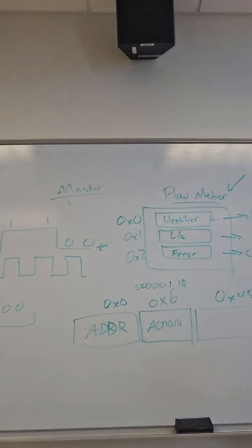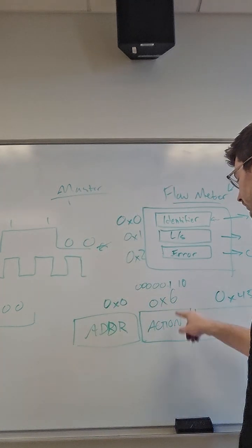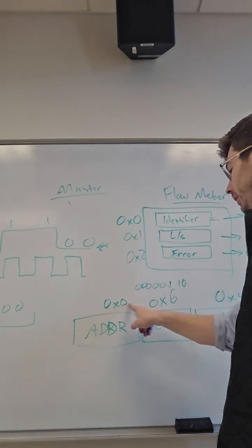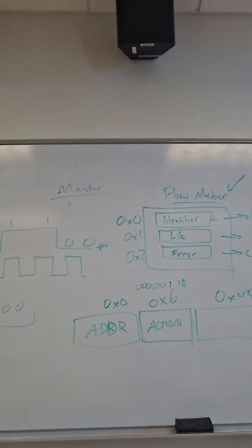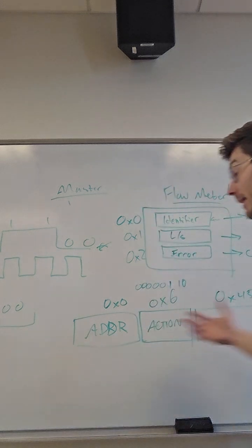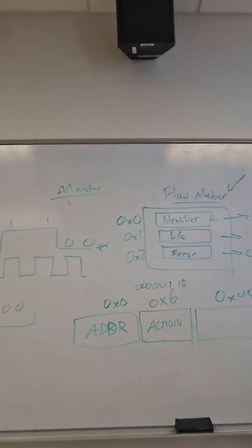What it's doing there is this is an 8-bit number, which means that we could have 0 to 255 different devices, right? Different combinations of zeros and ones. This is in hex. This is a 16-bit address, which means that you could have 65,000 different addresses, right? But in any case, this is the register.